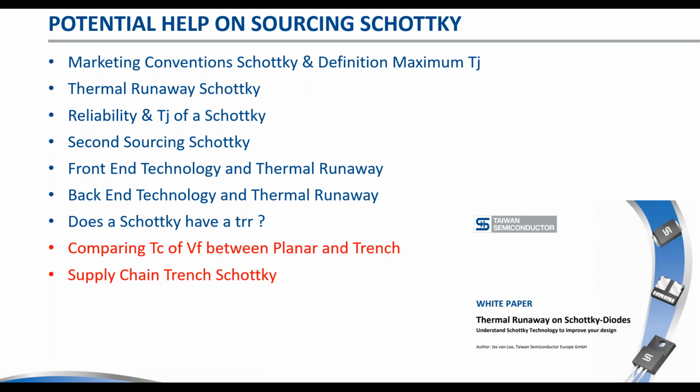So don't switch to trench Schottky unless you really have to, because of thermal runaway, or because you're really looking for efficiency gains or that type of thing in certain applications. Keep both in the back of your mind and evaluate them neutrally, and see also what your purchasing department may tell you about the comparisons between the two.